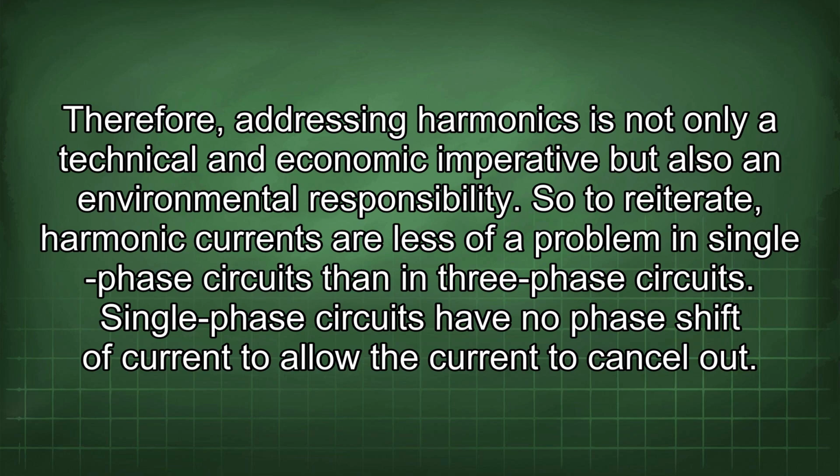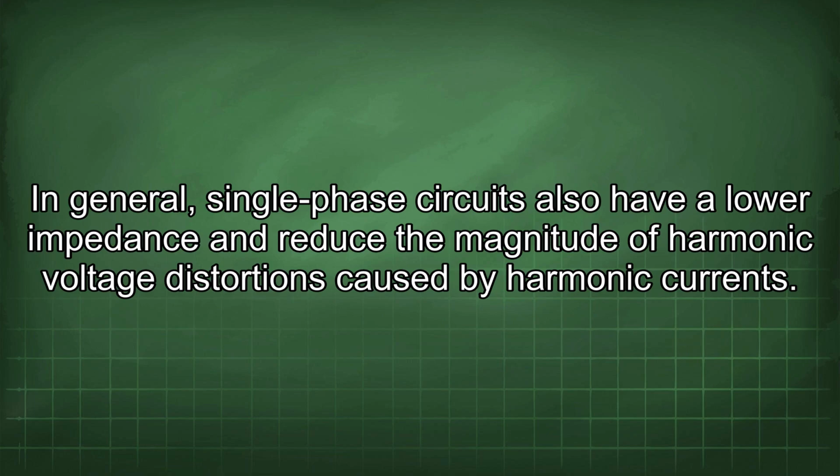So to reiterate, harmonic currents are less of a problem in single-phase circuits than in three-phase circuits. Single-phase circuits have no phase shift of current to allow the current to cancel out. In general, single-phase circuits also have a lower impedance and reduce the magnitude of harmonic voltage distortions caused by harmonic currents.